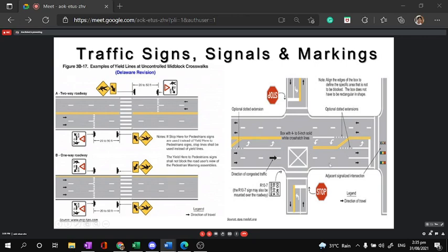On the right, you can see a more detailed pavement marking. So this is a yellow bar line for motorists to slow down. Stop on this line because this double line is for pedestrian already. And then you have division of lane, broken white line. And then this is a segment of smaller broken line. You can enter on this lane provided your direction is going left turn on this side. So this is left turn lane, outer lane, and middle aisle lane.